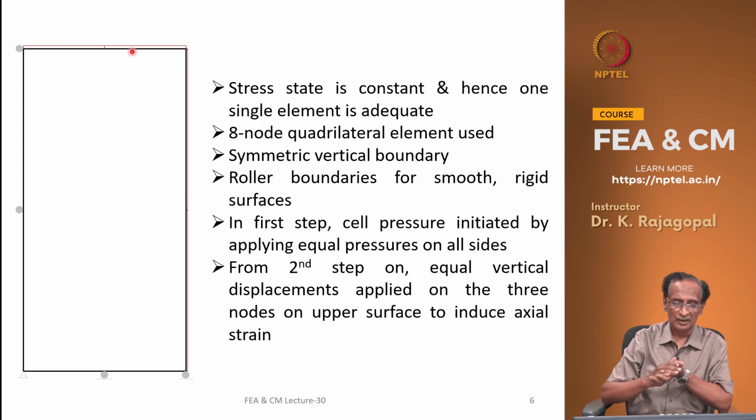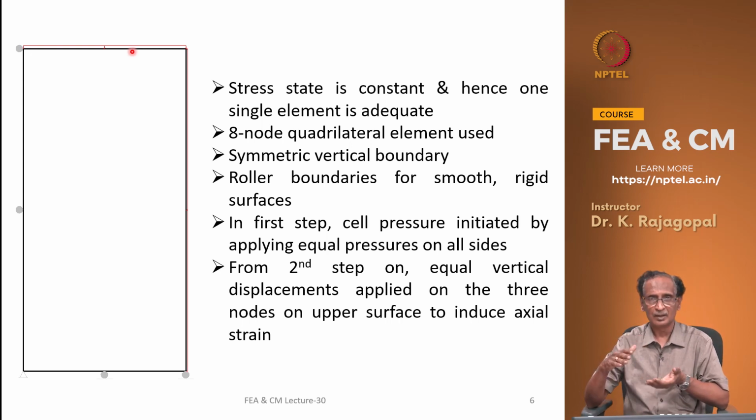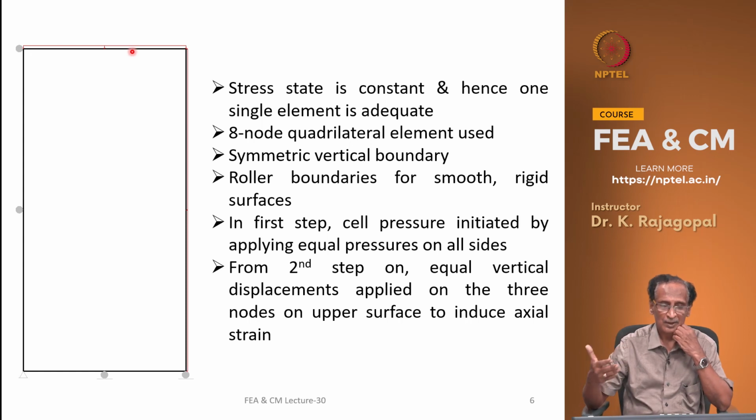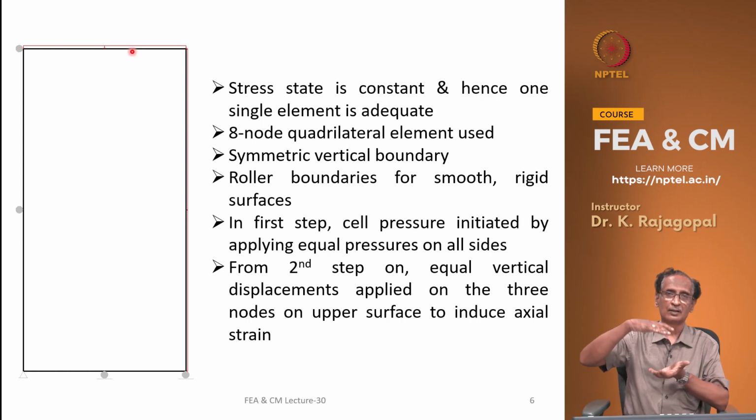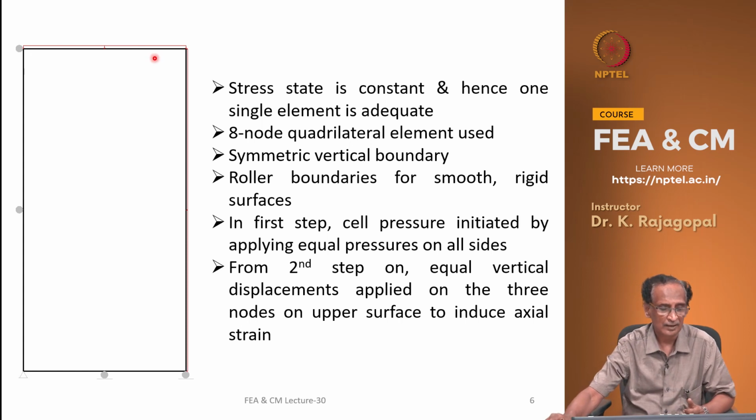See, we can do this test either with the load control or displacement control, but in the laboratory what we are doing is actually a displacement control. We are applying some axial strain and then measuring the reaction force through the proving ring, and the same thing we can do in the finite element analysis.